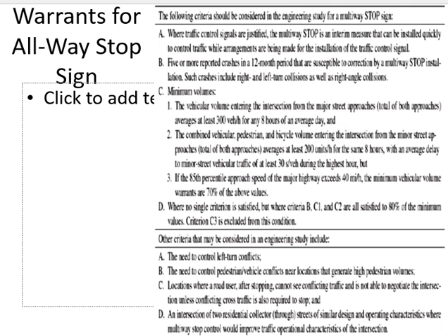So see what they are saying. The value is what? 300 vehicles per hour. For how many hours? 8 hours. So there are 8 hours in which the value remains this or more. Got it? It's a per hour value, but the volume is more than or equal to this value for 8 hours of the day. Clear? So it's a minimum for 8 hours of the day. For all 8 hours, the value is 300 or more, for the major road.